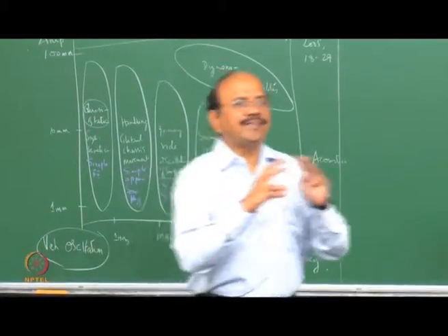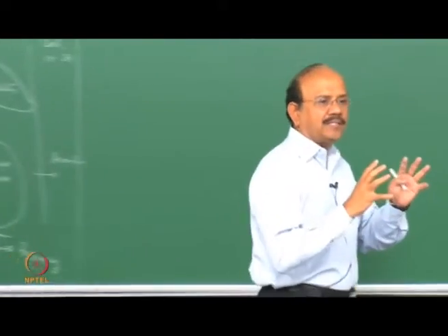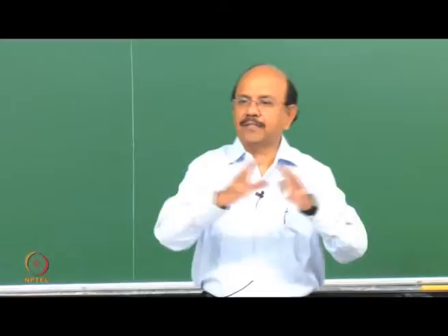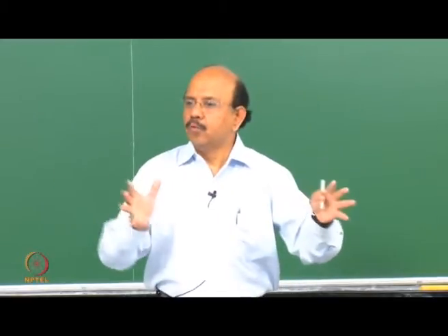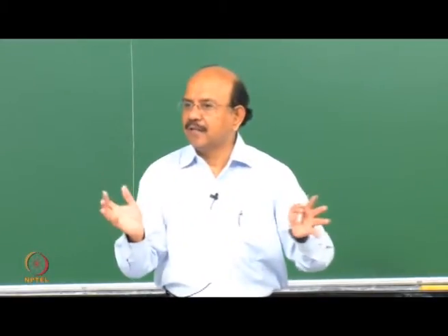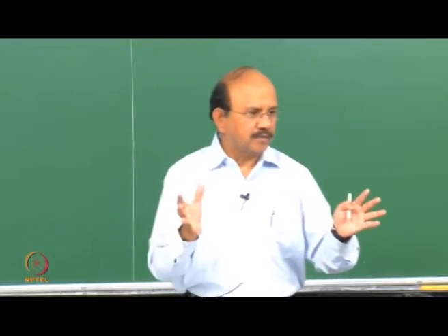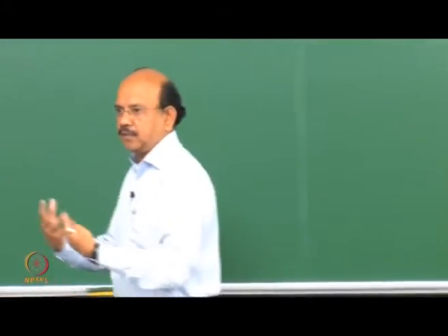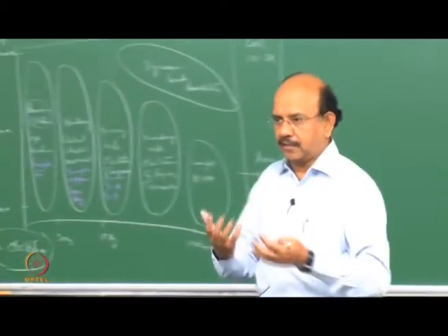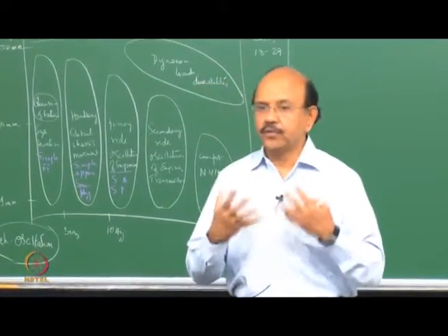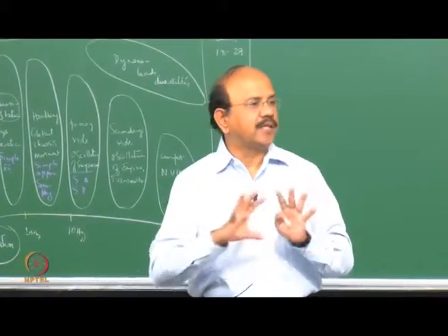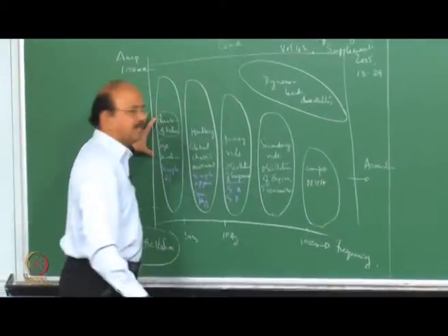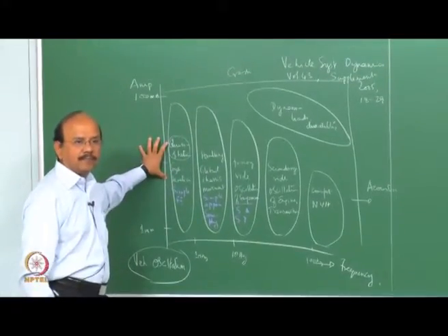So you use that kind of concept to understand, when you give a steering input, how the steering linkages move, what is the arc that it covers, and all those kinds of things. You use the fundamental concepts in theory of machines or kinematics of machinery which you studied in order to understand that. So that's the quasi-static models.